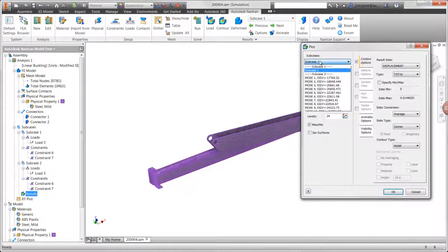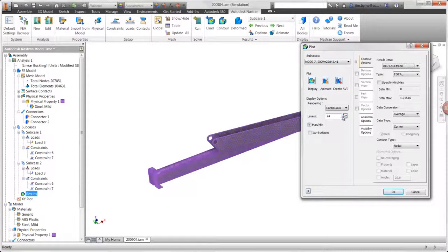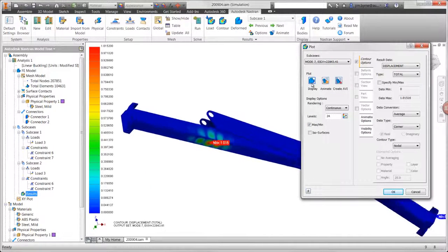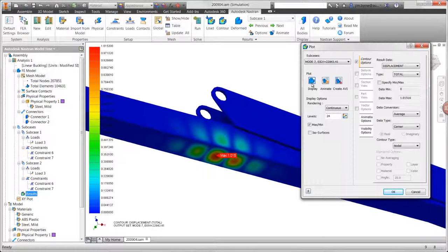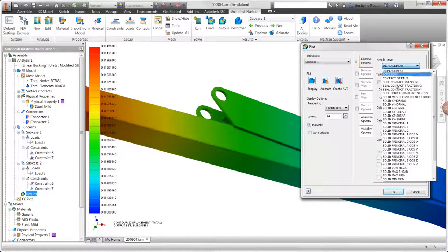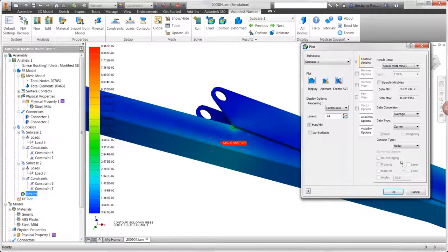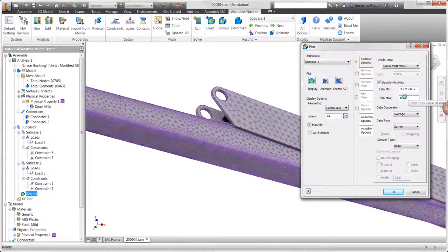We are now seeing load factors of over 22,000 newtons, meeting our engineering goal mentioned at the beginning of the video. It took minutes for us to view the results from the original design and make the necessary changes, as opposed to days to create a costly physical prototype. We can also see that the stress results have decreased to a factor of safety of 2. Remember, this is only a 1 Newton load. The highest stress can be multiplied by 1500 to compare to the previous results.